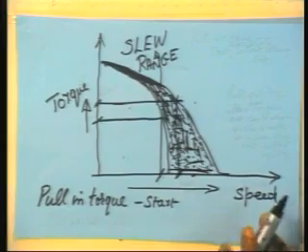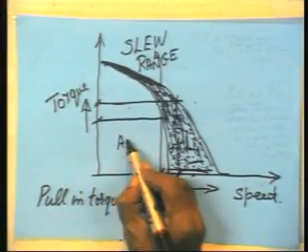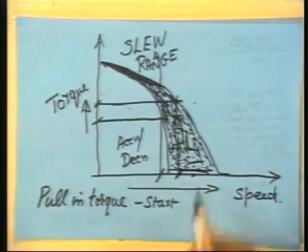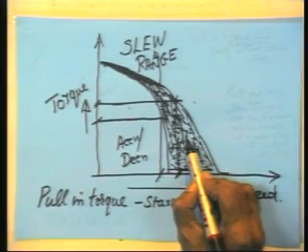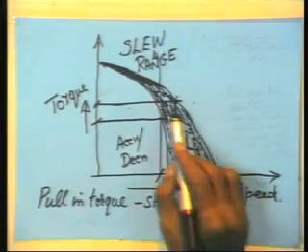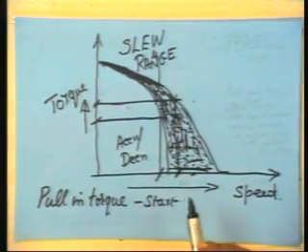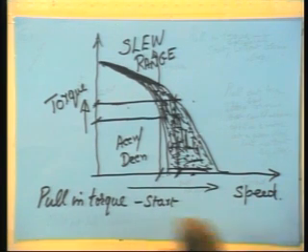So this is the acceleration deceleration zone. Here, if you are careful, your motor will not miss steps. If you are not careful and cross this boundary, asking for more speed, then the motor will start missing steps. These are the 2 points you have to remember.